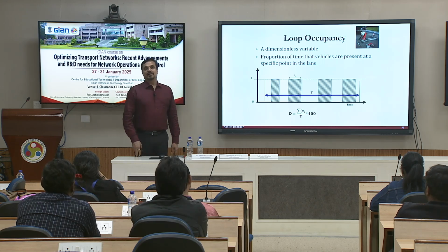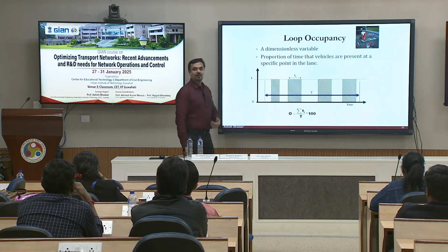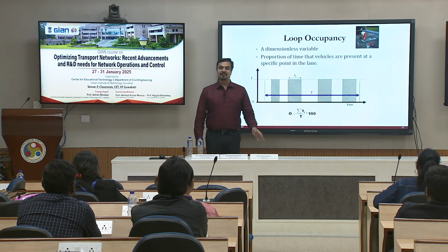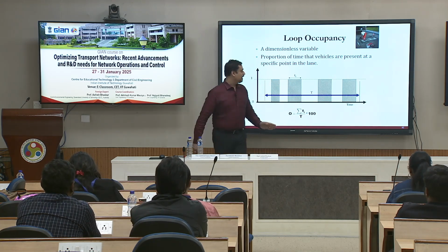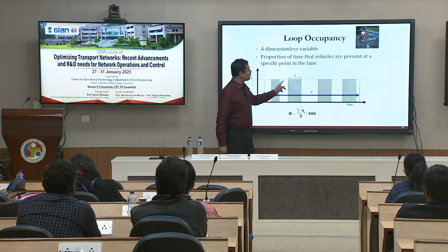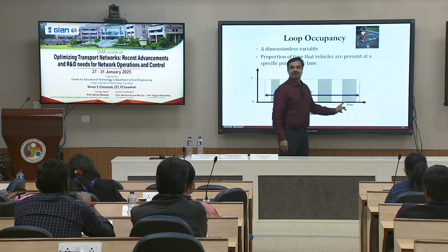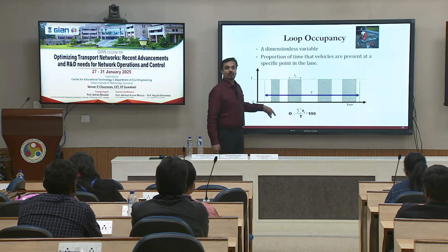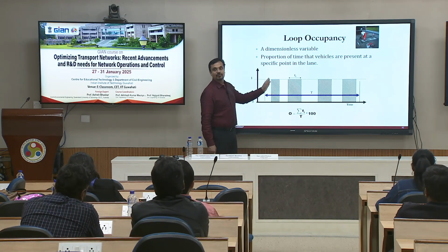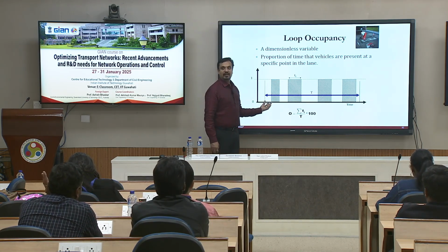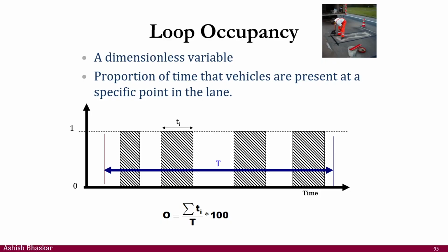Yeah. If this is happening, then the drivers are not respecting your red light, they are just entering the intersection. During the red time we do not expect that; if a vehicle has arrived, it should be 100% after that. It stopped and go, right, you will have high occupancy. So, the first time you have a pulse of 1 represents the time when the first vehicle has arrived. If I look at the initial certain time period of my red, that occupancy will tell me how quickly that vehicle has arrived.